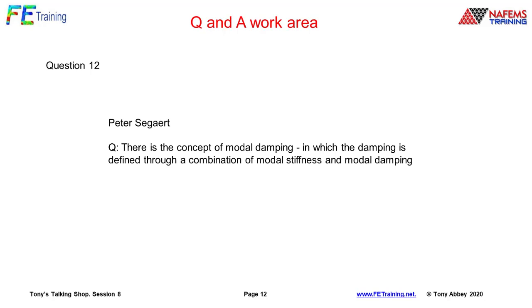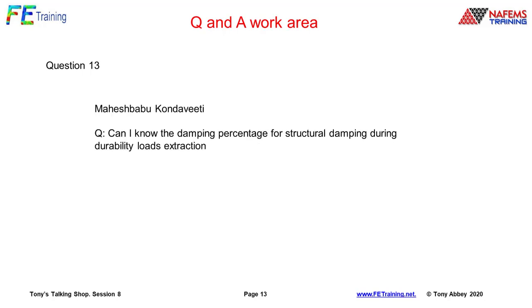Can I know the damping percentage for structural damping during durability loads extraction? Again, it's something that we can only really nail down if we've got some test evidence. So unfortunately, we've got to go for test to give us a good value for damping, or previous experience and so on.